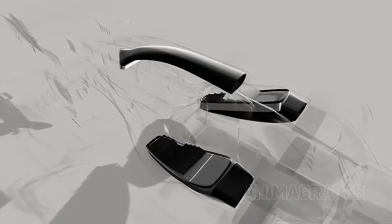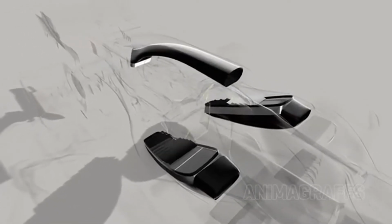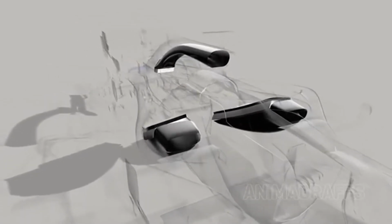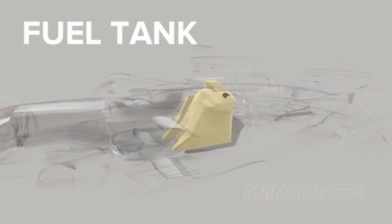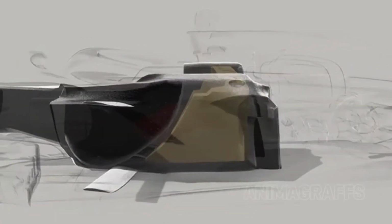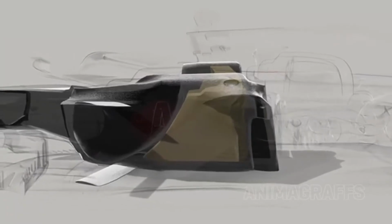F1 teams may locate specific radiators in different positions than I've shown here, though the general available spaces will be similar. They may also use water-driven intercooling for turbo air, in contrast to the simpler air-to-air setup I've chosen. Fuel tank. The fuel tank, also called a fuel cell, is a nearly puncture-proof Kevlar bladder lined with rubber. It occupies an isolated compartment in the carbon fiber monocoque shell and fills all available space.